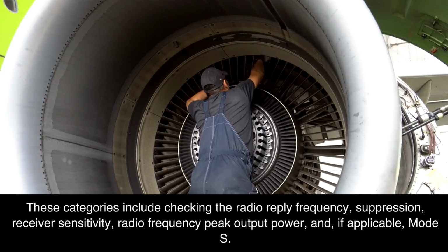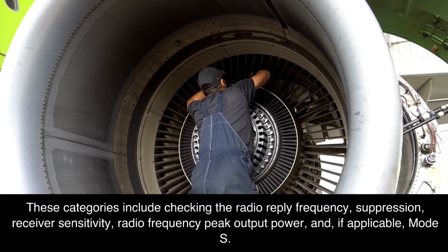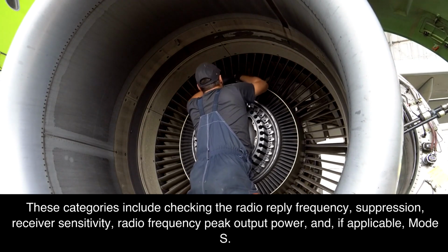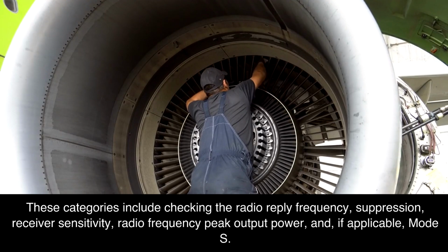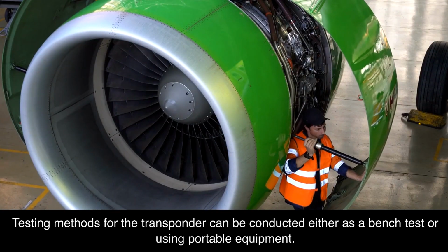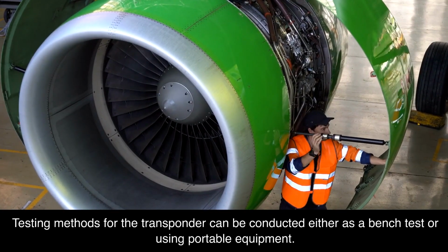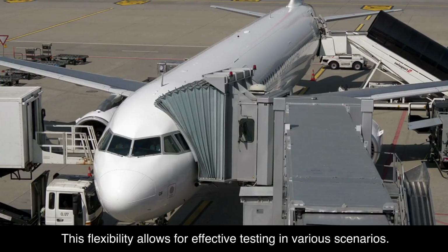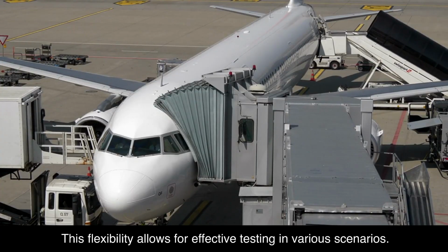These categories include checking the radio reply frequency, suppression, receiver sensitivity, radio frequency peak output power, and, if applicable, Mode S. Testing methods for the transponder can be conducted either as a bench test or using portable equipment. This flexibility allows for effective testing in various scenarios.